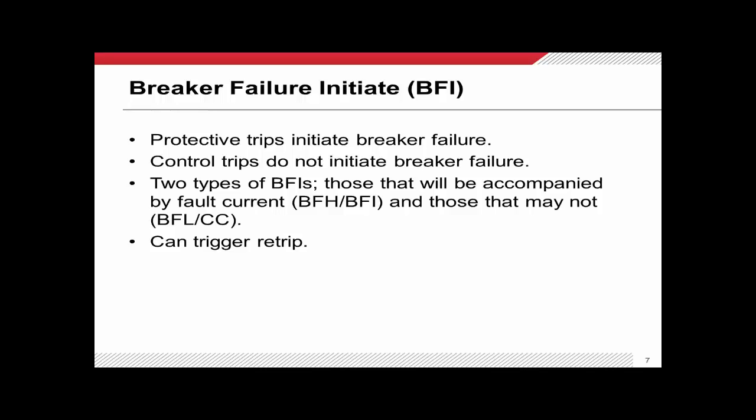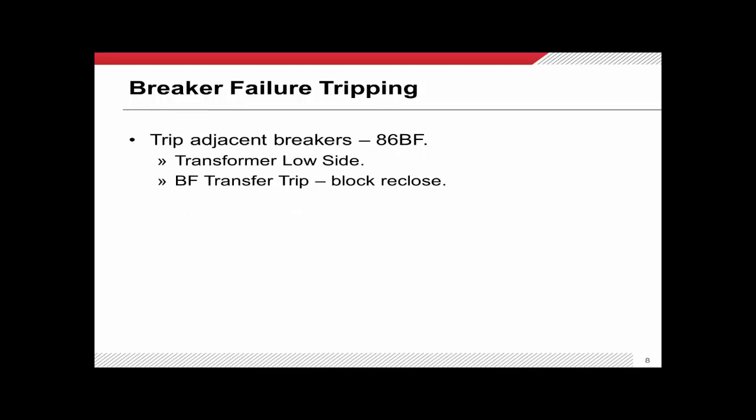And remember what I said a few minutes ago, one of the most common causes of a failed breaker is some problem with the DC source. And this recognizes it, and I think this is a really cool, really slick approach to improve the certainty that your breakers will trip when called upon.